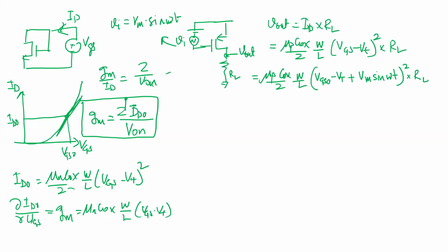So the voltage here is this equation here, right? Vout equals ID times RL, and RL is obviously linear, so this is the total Vout, okay? So if I'm looking at the Vout, it's sitting at DC, and as I give this audio signal, it's kind of amplifying it, okay? Got it? So that's the simplest amplifier, common source amplifier.